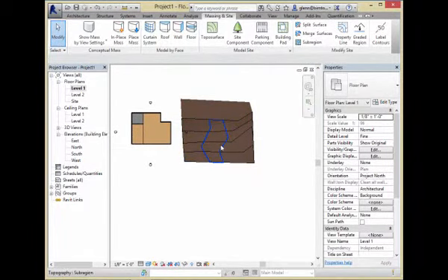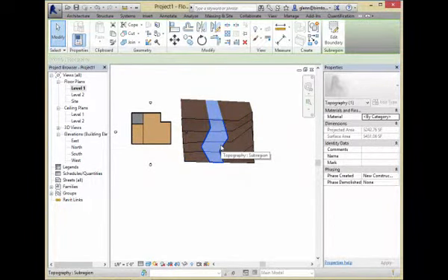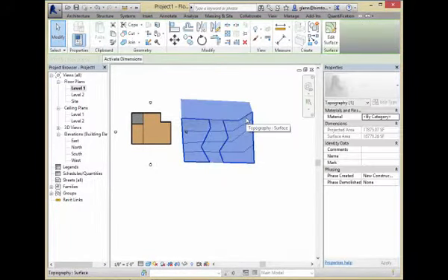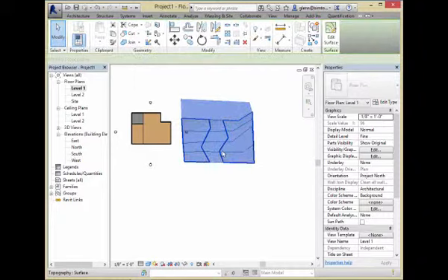So now what can we do with this? This little chunk right here is considered different. So if I wanted to change its materials, the overall topography has a material that's determined by category. The category of the material that's displayed for site generally is something called earth. If I want to change the material just to this little path within here, as opposed to being by category, which is the default material for this category, I could choose that little guy.